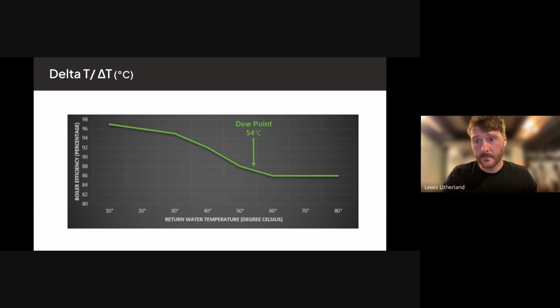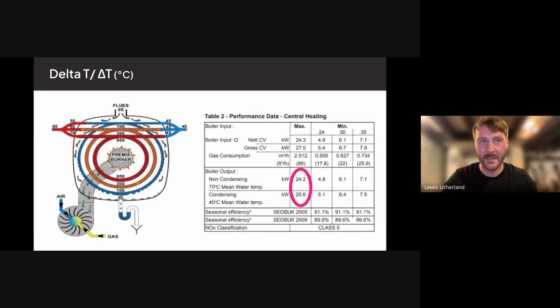Without going too far on this, you could spend $2,000, let's say, repiping the full system in this scenario and replacing every radiator to get your flow temperature down by 10 or 20 degrees. And then you look at this table and you go, great, I've spent $2,000 and I've raised the efficiency by 5%. What does that equate to in money that they're spending every month? Well, nothing. What was the point? If you did that with a heat pump, suddenly it shot up, and it just becomes a little bit more interesting anyway.